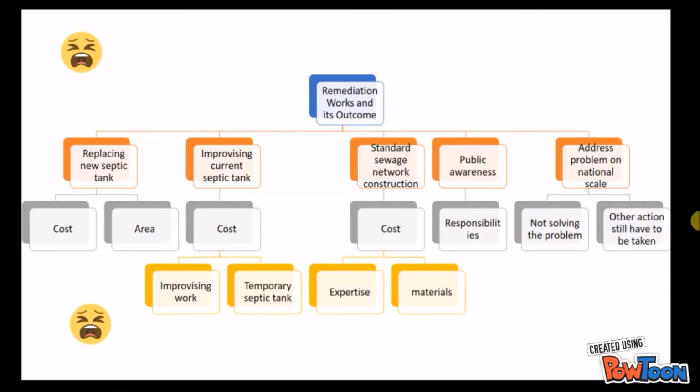Based on the estimation, 6 stories of 3 buildings will produce 360 p. The 3 meters of diameter and 10 meters length closed underground septic tank will be used with the estimated Malaysia price of RM 150,000 per unit. The system constructed will then have to be maintained and supervised to ensure the system and structure are working in good condition. This has to be included in the cost for the remediation work.